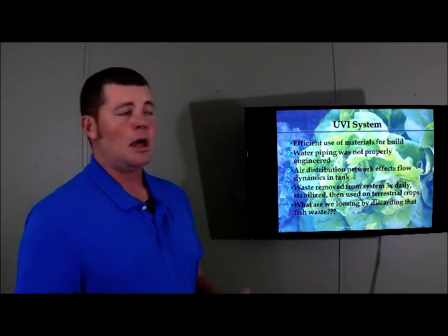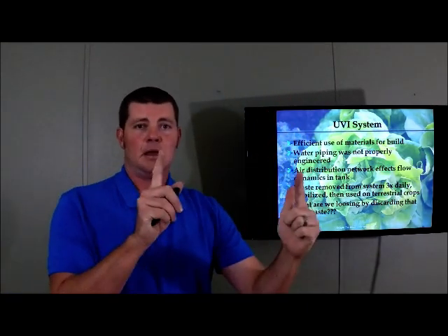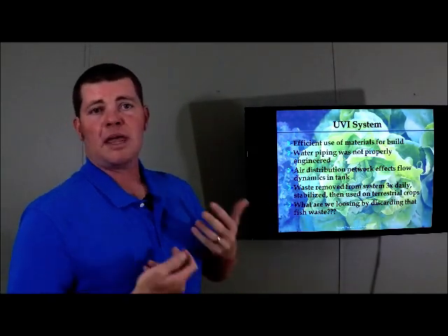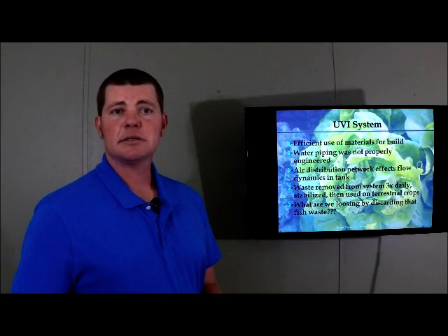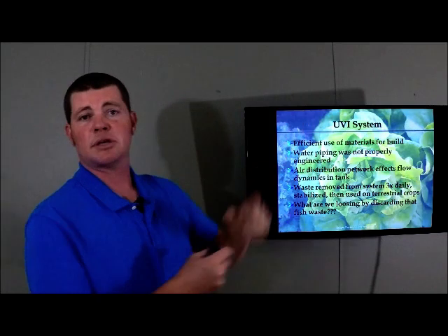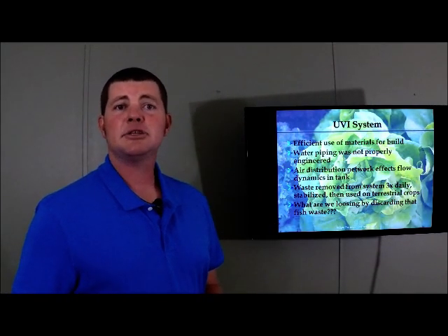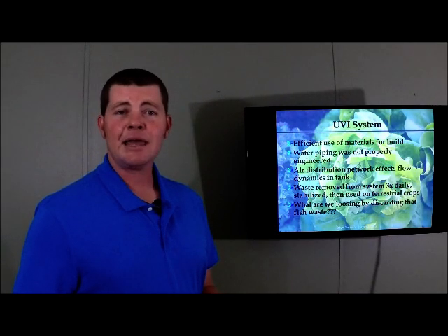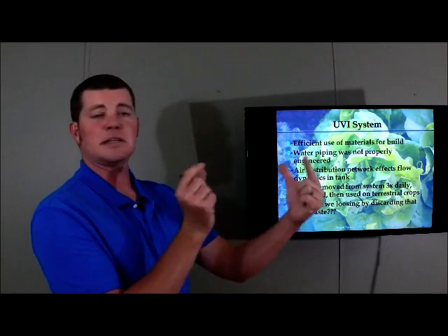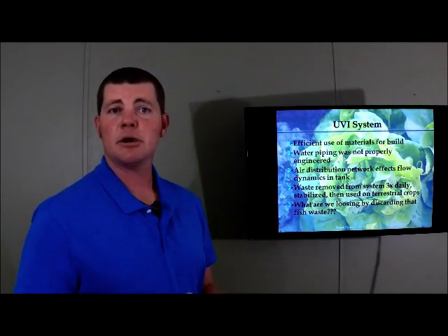So that's no good. The second thing is that an air stone should always be placed flat, not up and down, because as you know, air will flow the path of least resistance. And if you have an air stone hanging vertically, the majority of the air is going to come out of the upper portion of the stone, leading to larger, less uniform bubble size and less transfer of oxygen into the water column. So you want those rectangular stones flat so that you have even distribution throughout the stone and even airflow.